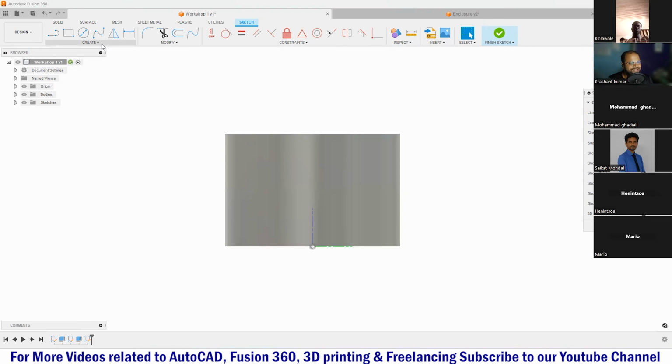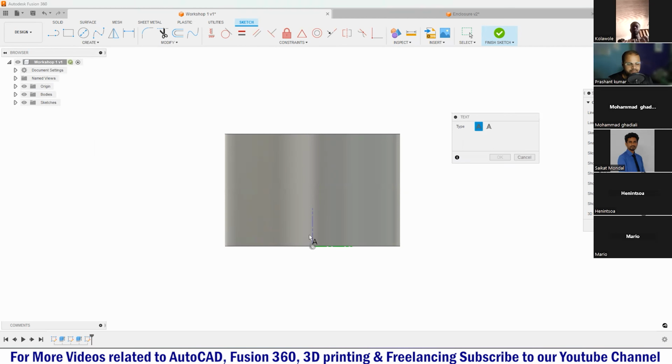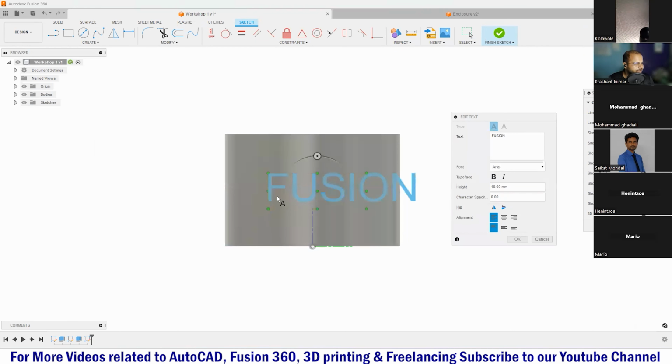And here I'm going to write some text. So I will go to my create panel and activate my text tool like this. I will create a text box and start writing some text, for example, sample or Fusion, like this. And then I will press OK. Then I will right click on the sketch, double click on my sketch, and try to move this sketch a little bit.